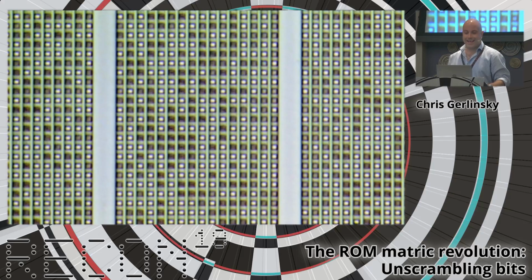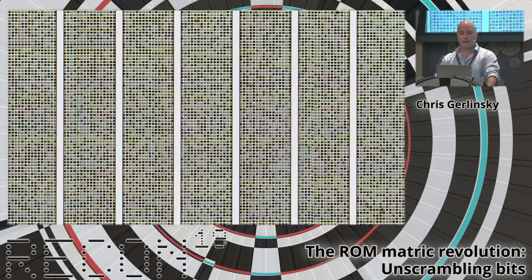After doing a selective etch on the ROM, a dash etch it's called, now we have some contrast within the bits, and we can actually extract the bits visually from this image. Wider view after doing some contrast adjustments. So in this case, the fact that it's implant ROM wasn't really a problem. You're still able to visually see the bits under the microscope.